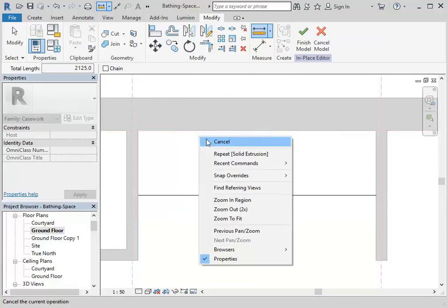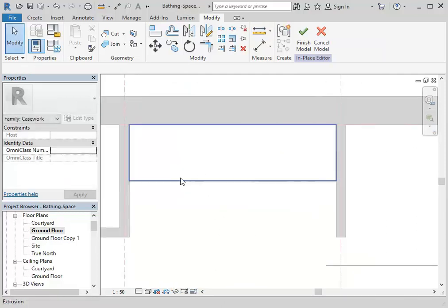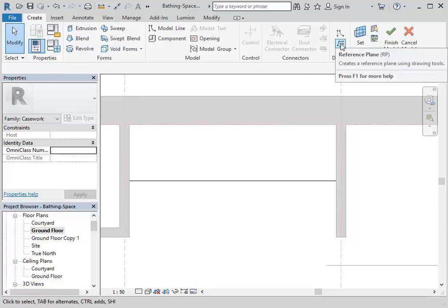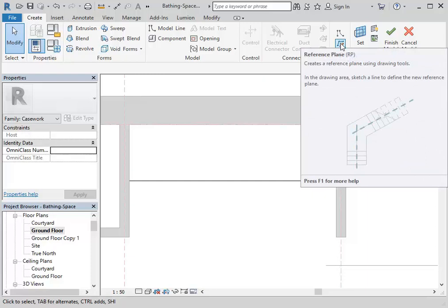And what do you think I'm going to use to help set out the spacing? Exactly, that's right. Reference planes are going to help a lot. You've got this great option when you're working with model in place. Back on the Create tab, you can make reference planes. They give you the right tools as you're using these other sub-objects.